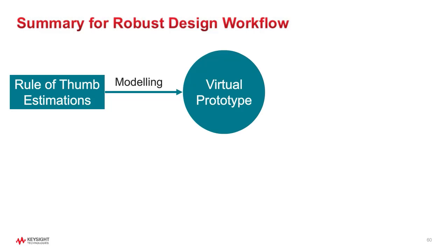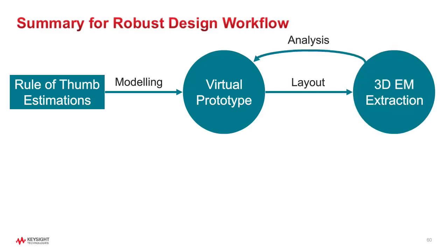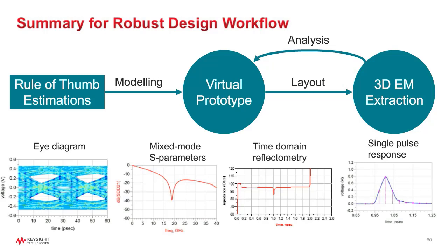After that, we looked at the layout. After the layout, we did some 3D extraction. And between the virtual prototype and the 3D EM extraction, we saw this behavior of virtuous cycle, where once we know one and the other, it's very easy to perform what-if analysis, troubleshooting, and do design exploration. And in the process, we looked at eye diagram, mixed mode S parameters, TDR, and single pulse response.